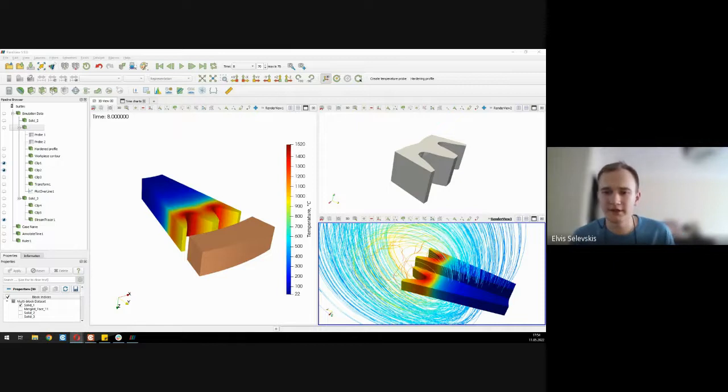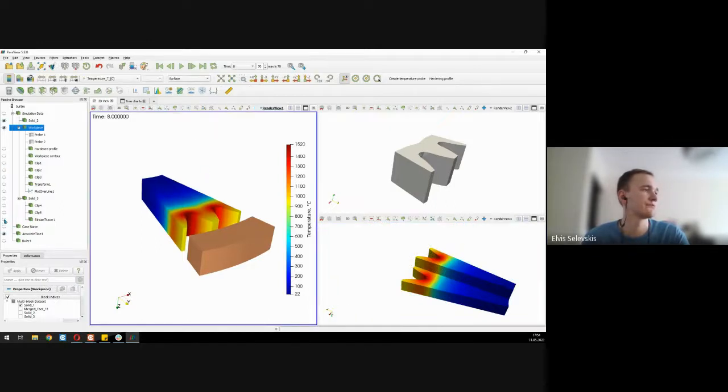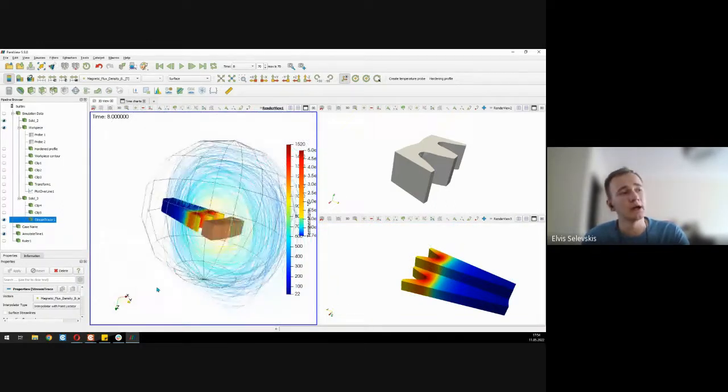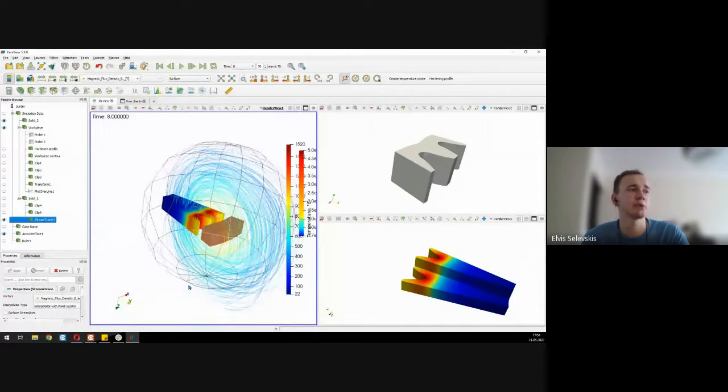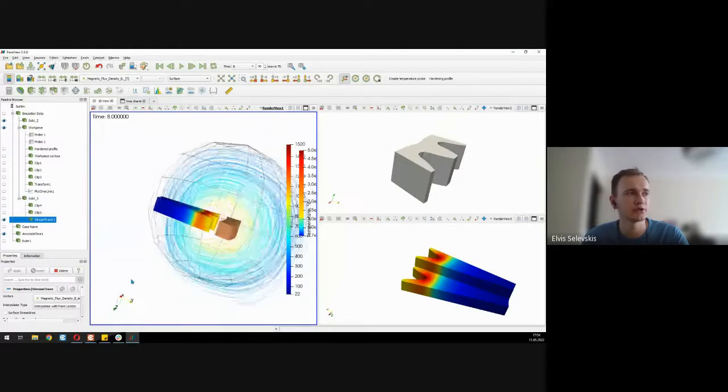Okay, I see that there are a couple of questions in the chat box. What effect does the size and position of the sphere play in the stream tracer filter, and should the sphere be larger than the area of focus? The size of the sphere, I can actually just show you that as well. The size of the sphere will also impact how long the lines are in general.